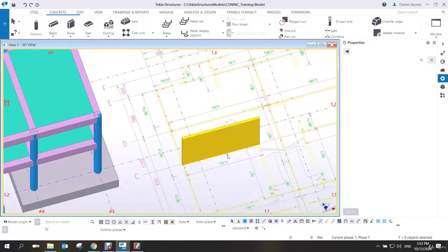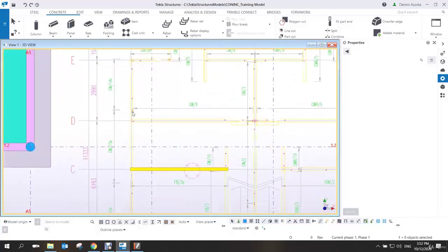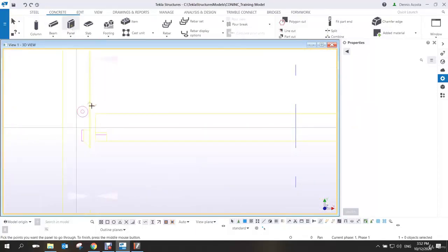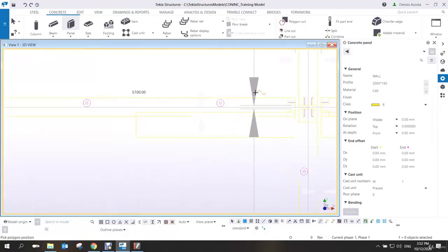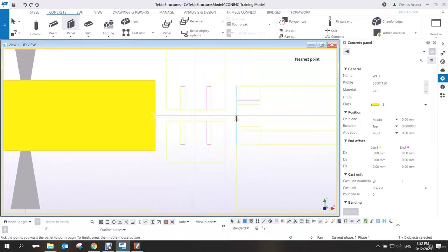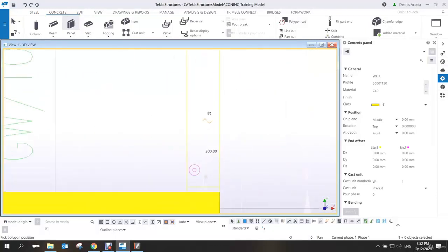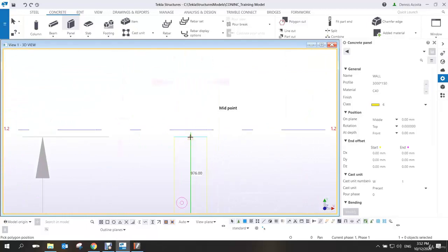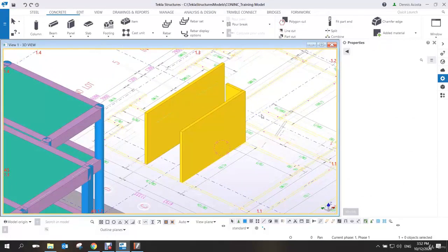So meaning you don't need to use a lot of construction points to model, because it's already there. All you have to do is simply place here. Let's say here again 1, and then here up to where? So you can see here up to here, middle button of your mouse, and then from here continue working, let's say here 1, and then 2, middle button. At the end of the day, you can have the walls here. So that's how you use the AutoCAD.